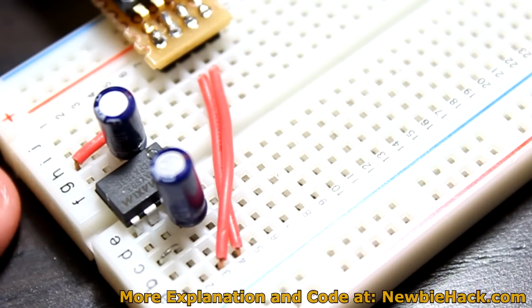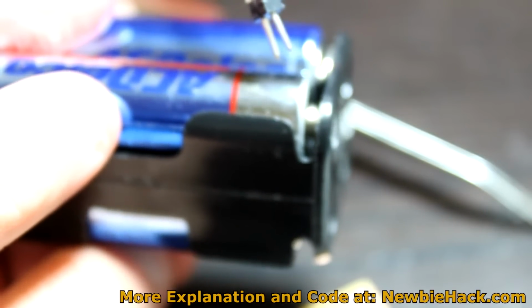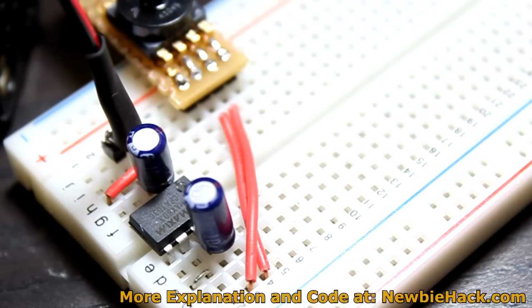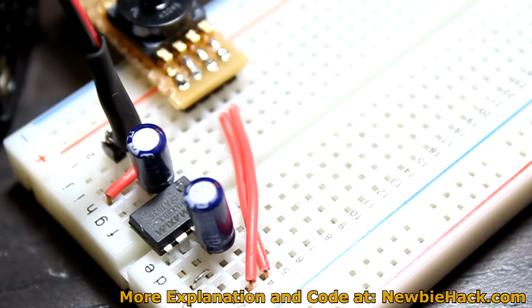Okay, so we have supply to the sensor. Now we're going to use a battery like this, a set of batteries. It's 4 batteries with 1.5 volts each, which makes 6 volts. And we'll plug that into the input side, and making sure that the red goes to the pin number 1 here, and the ground black goes to pin number 2. So now we're supplying voltage to the regulator, 6 volts in this case. Through the regulator we'll get 5 volts, and we're supplying the sensor.